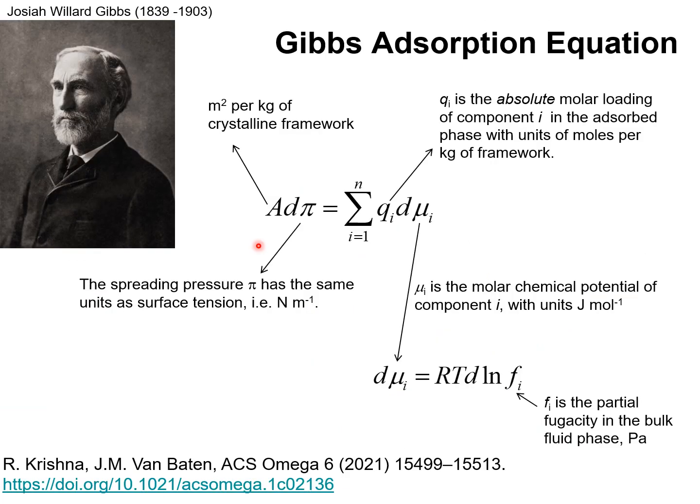The description of the thermodynamics of mixture adsorption begins with the Gibbs adsorption equation, written in this form: A times the differential of pi equals the sum of the product of the molar loading of component i times the differential of the chemical potential of component i.